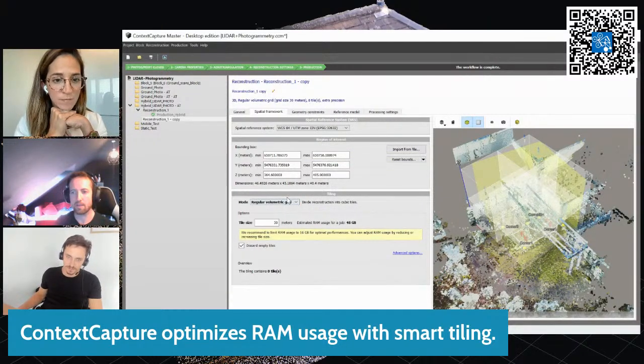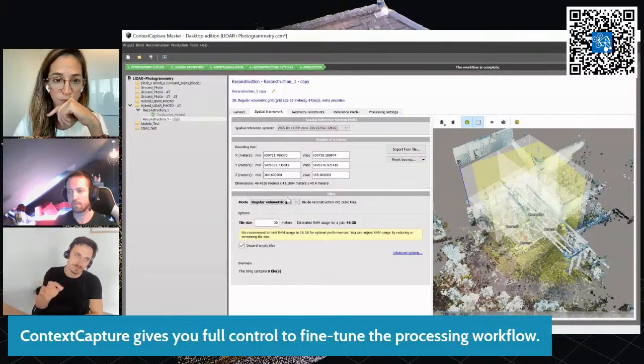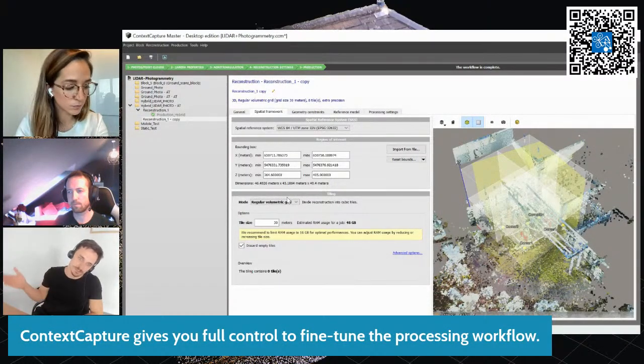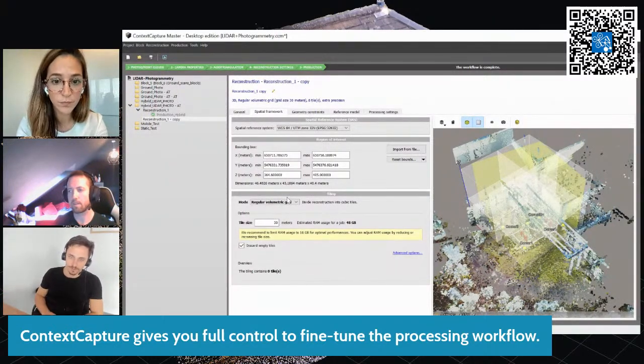Especially if you have a project outline, like a project brief. It can also be converted from a DGN file. Let's say the customer says, I have to have these strict borders, and it cannot be 1 centimeter bigger or smaller. That's not a problem, because you load it in the ContextCapture editor, which opens everything actually, convert it, and then load it as a border here without a problem. Okay. There is also, is that the surface constraint or is that actually the boundary?